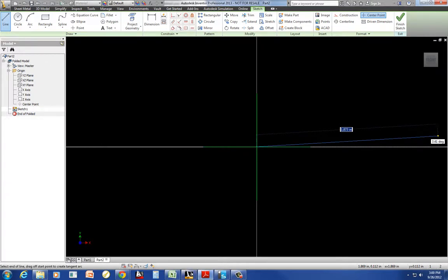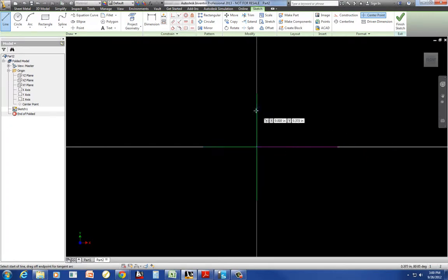that, let's go over here to the drawing and see what that's going to be. It's going to be all the way to the end. I'm just going to do this. I'm going to just kind of draw in a shape. And notice that I'm not letting these snap vertical, because if you let that happen, then it's going to put that constraint on there, and it may not be that way. But I am going to let these be tangent.